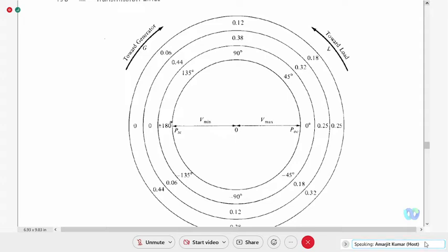And the three scales: outermost scale means we are measuring distance on the transmission line from the generator. Middle scale means from the load end, and innermost scale is a protractor, so it will give the angle of the reflection coefficient, theta gamma.